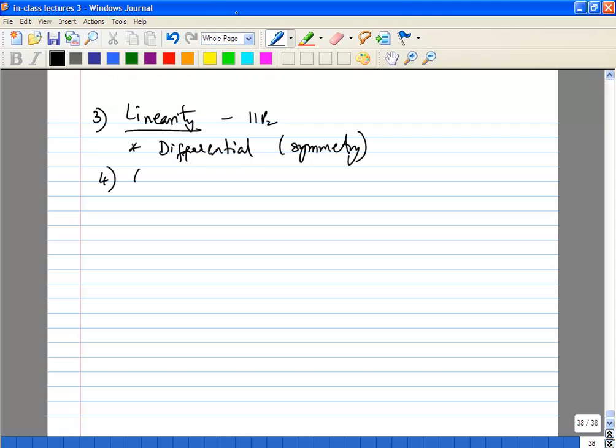Then one last thing to be careful about is in your gain path. Remember, in the case of the heterodyne, you can split the gain between your RF and IF. So there you have three places, RF, IF and baseband. Here it's just RF and baseband. So you will have a significant portion of the gain coming from the RF side. So what you have to be careful about are parasitic paths, because the minute you have large gain, if you have parasitic feedback paths, you can have stability problems.